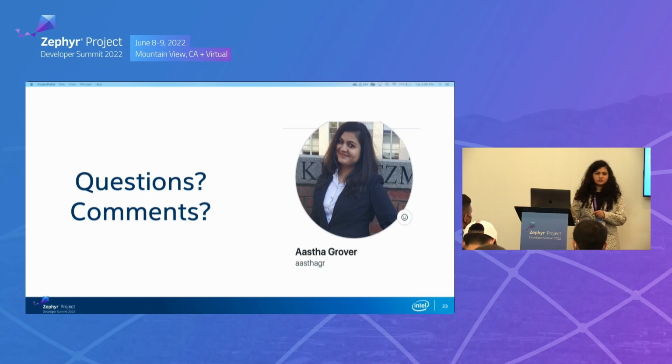So this is Twister. This is testing, and this is an automated way of saying that there would be hardware testing enabled. You'll not do that for every single test case with Twister. But if I go underneath at the low level, if you just use the West build command, you will just build the executable or have your binary when a specific test case or a sample is built, and then you flash it on the drive to the device.